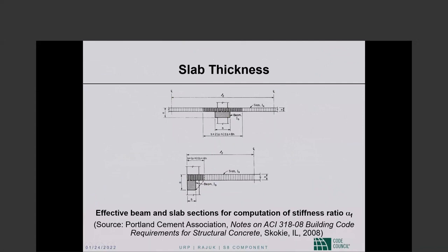The slab part is clear. What is the beam? There is a beam sticking below the slab, but a portion of the slab is also treated as part of the beam. And that portion is equal to whatever is sticking below the slab, that is h minus hf.